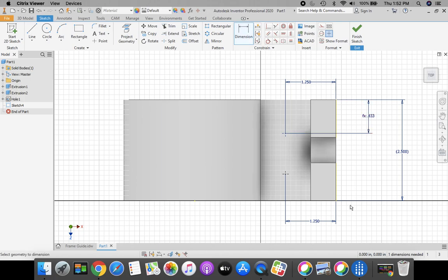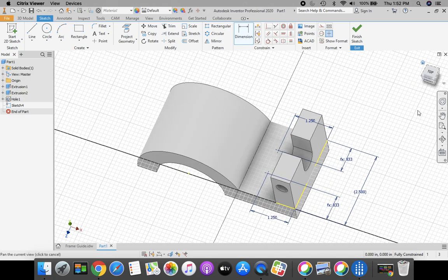We're going to dimension again, do the same thing to the bottom. Go from the bottom of the block to that bottom point, bring that out. And I want that same dimension again. I want the overall dimension, this dimension in parentheses, just click it. And I'm going to divide, which is backslash, and then 3. Green check mark. First driven dimensions. Nice job. I'm going to go home.